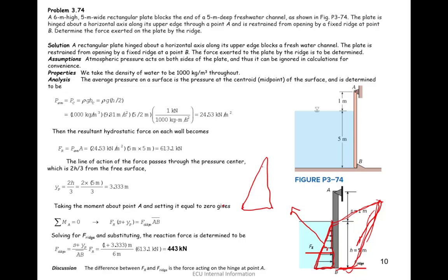So the centroid of this triangle is where the force is acting. If this is H, then from here to the centroid of this triangle is 2/3 of H.